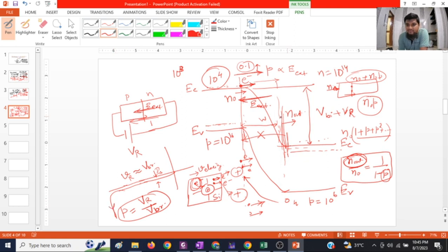A lot of electrons are being created on this side. Likewise, whenever one electron breaks a bond, one electron is created, and one hole is also created over here, isn't it? One electron has been knocked out, so one hole is also created, and this hole will accelerate on this side. It is also possible that these holes will create another ionization, because effectively one electron over here will accelerate to fill this vacancy.